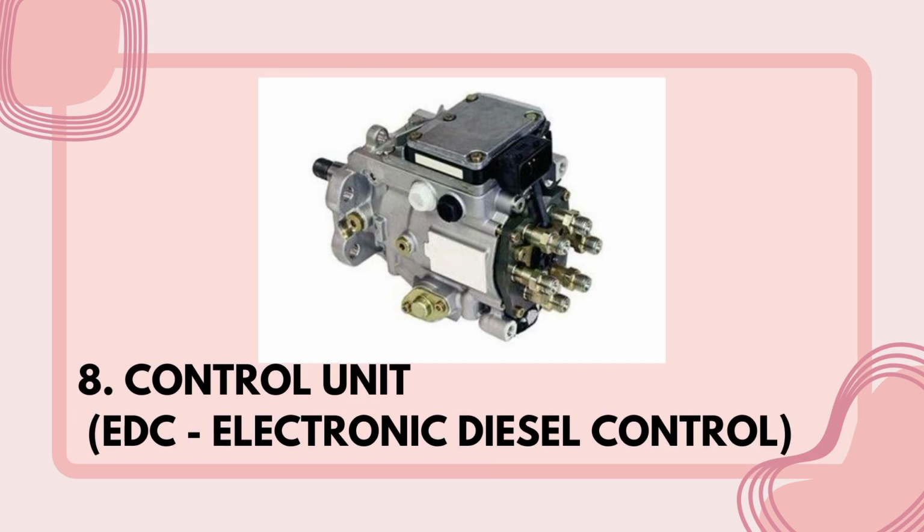The next part is the control unit or the electronic diesel control, EDC. This is the engine's brain for fuel management. The function of this is to receive input from sensors: temperature, pressure, speed, accelerator pedal. And it also adjusts fuel delivery and timing for efficiency, power, and emission control.